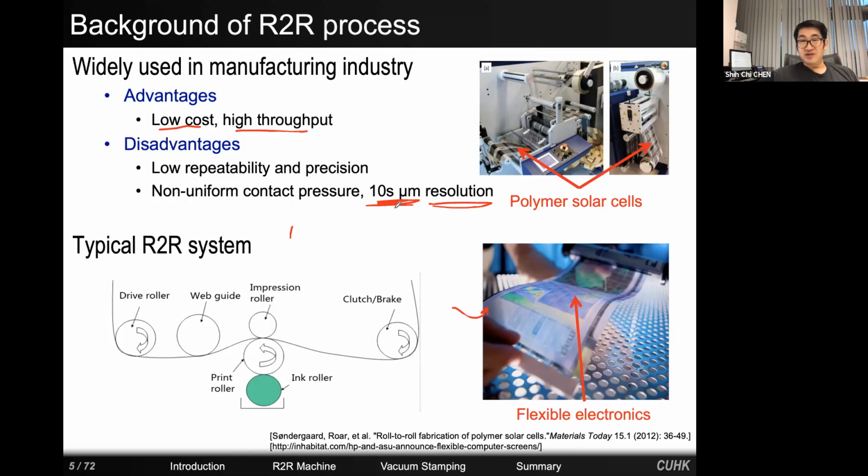As I explained, you really want small features and good alignment between the gate and source layers to achieve high switching speed and low power. Roll-to-roll has been demonstrated in PV panels, photovoltaic cells, because the electrodes can be printed without high requirements on resolution. But electronics like transistors is a killer. It must have that resolution in order to achieve the desired function.